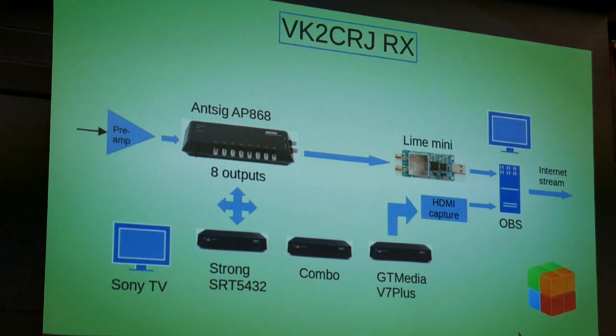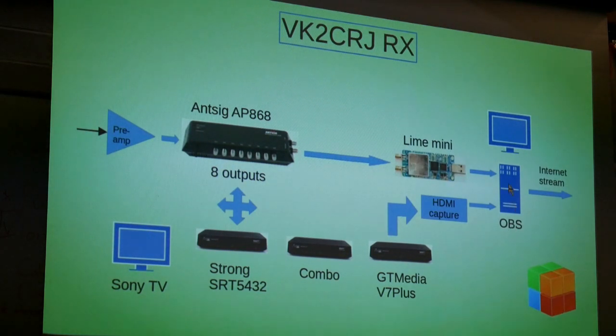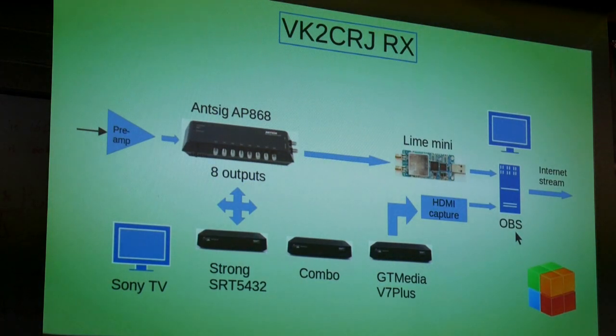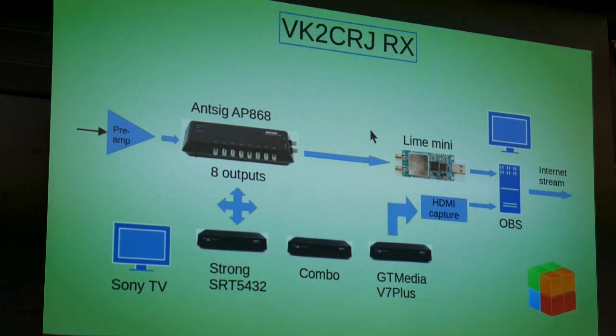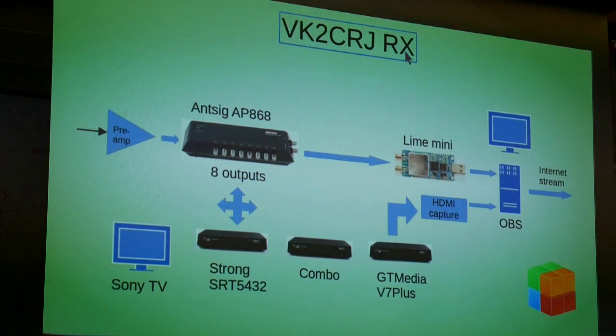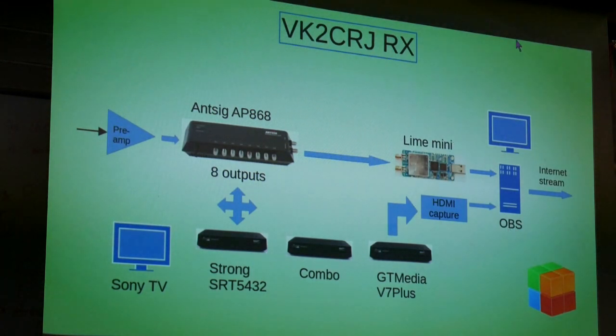But you didn't run any decoding software on that? Didn't run DVB-S or DVB-T decoding on that? No. SDR Angel can decode DVB-S, but can't do DVB-T. It just needs too much grunt. It's just too much processing to do for DVB-T. You can imagine you've got to do that big FFT and fast. You can do it, but it's a challenge doing all that in software. So he hasn't done it yet anyway.